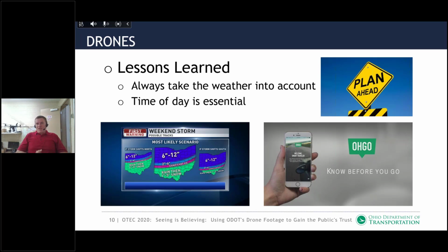So I was going to go ahead and wrap up my little talk about drones with some lessons that we learned. First, we knew that the weather is going to affect flights, but we found out that it affects more than just our ability to put an aircraft in the air. For example, with snow on the ground around dark pavement, which I think will be illustrated in the video coming up, you can't actually see some of the vehicles as they move through the intersection, and so therefore we didn't get as much useful footage as we had hoped.